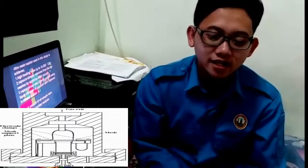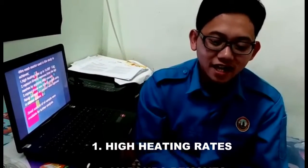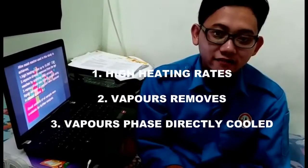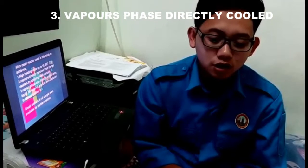Okay, the wire mesh reactor was also used in this study to achieve high heating rates up to 10 degrees C per second. Vapors were directly removed from the hot meshes by applying deep vacuum. Third, the vapor phase was directly cooled using liquid nitrogen. All products were captured in a closed system, so a small amount of oil sample was available for further analysis.